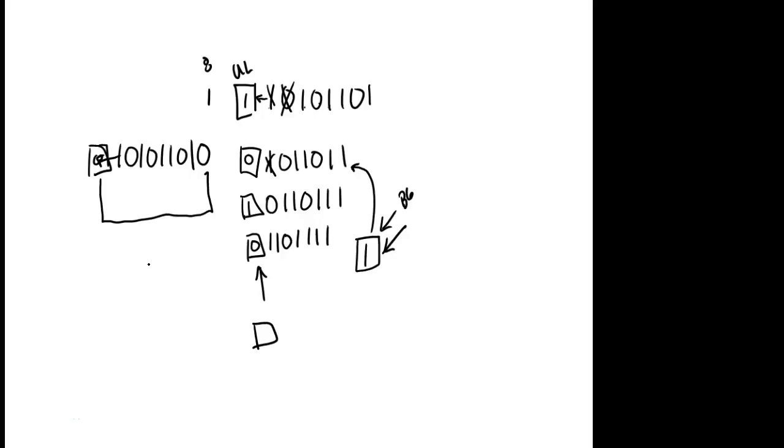So that means if I was going to make a sign flash like that, just in a loop, I would maybe load it with all fives, or maybe even 1 5, depends on how many lights I have out there, and I'd load 1 0 1 0 1, right? You understand? And then I would take the contents of my unload bit and loop it back around. And then we can make a sign go this direction, we can make it go that direction. We can make strobe lights at the airport, just constantly do what?